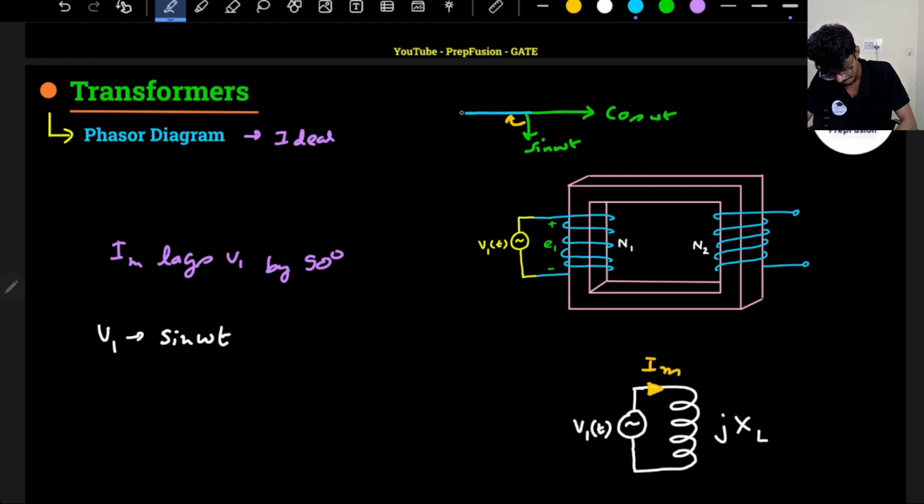So this will be here. What is this? This is basically minus of cos omega t. So my flux phi of t will be some phi m into minus of cos omega t. Not flux, sorry. My current, the magnetizing current, will obviously be an AC quantity, because everything is an AC quantity. It will be some I max into minus of cos omega t. Basically, it will be proportional to negative of cos omega t.